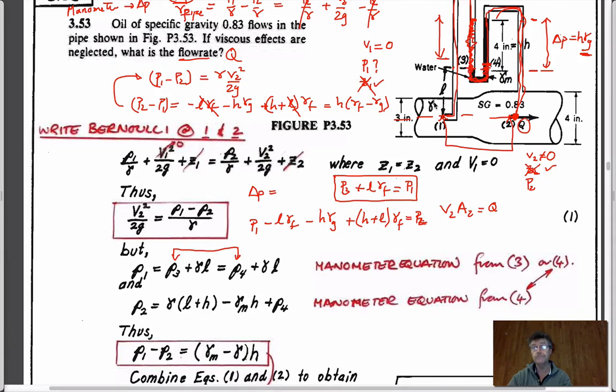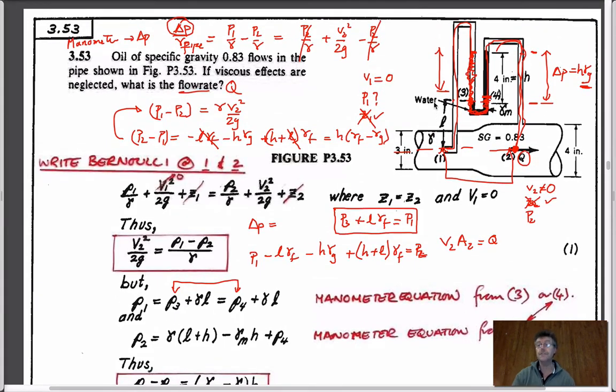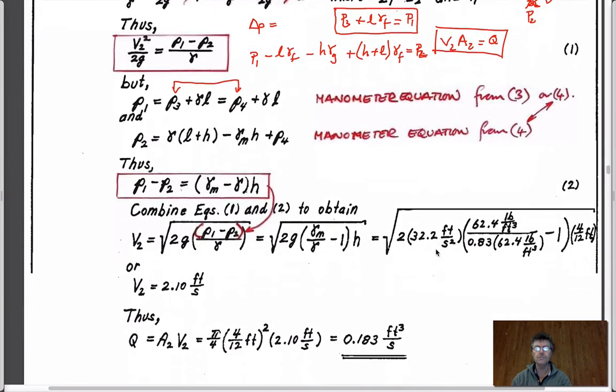Okay? So the bigger picture for this: write Bernoulli's equation in terms of the two pressures, upstream and downstream. Solve the manometer equation separately for the delta P term. And when you substitute them together, you should come out with one value for this term here. If you know what V squared is, then you have enough to calculate the flow rate. So, are we losing people?